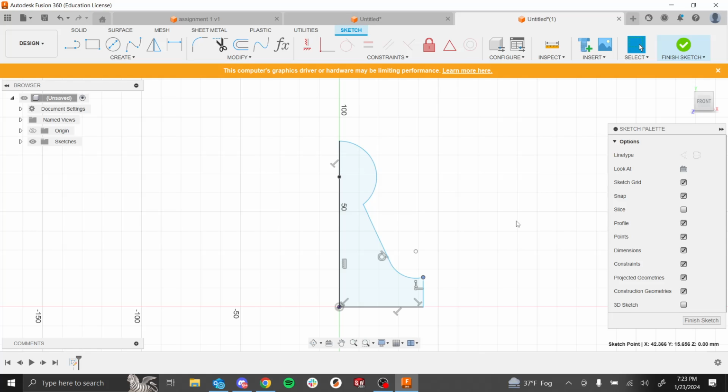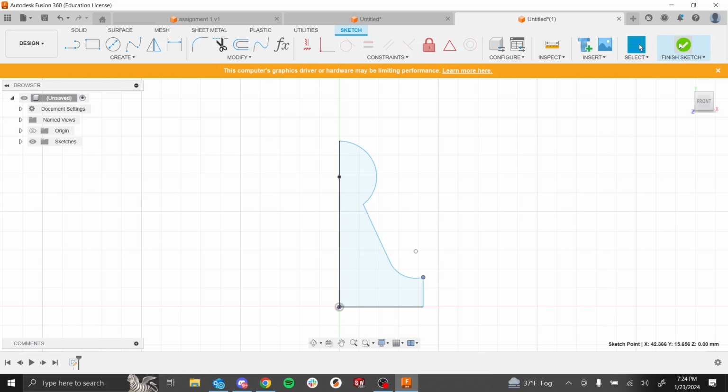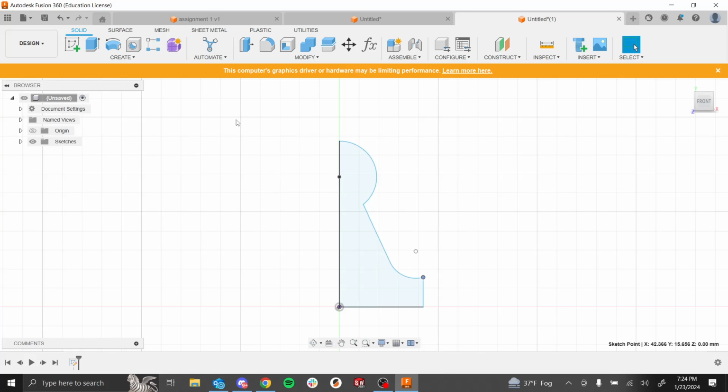But over here, we have this profile of a chess piece. It's almost like you cut it in half and you cut it in half again. Basically, we're going to revolve it instead of extruding it. Before, we've been extruding things, so we take a sketch and we pull it. But this is taking a sketch and rotating it. I don't know if you've done the disk and washer stuff in calculus, but this is basically what the computer is doing. It's going to take this sketch and copy it an infinite number of times until you have a solid shape.